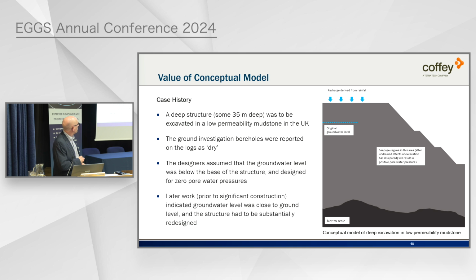And so in this case, if they were to excavate this cutting, obviously, you get an undrained effect when you load it. You get suctions initially, and then over time, a pore water regime would set up with positive pore pressures here. So it had to be designed.